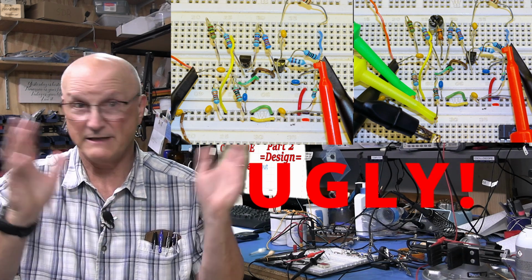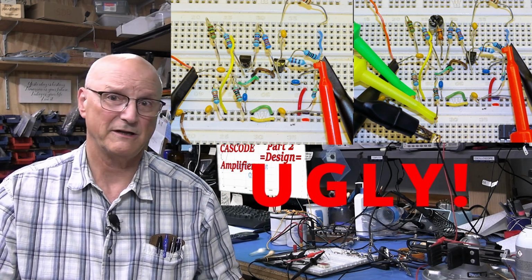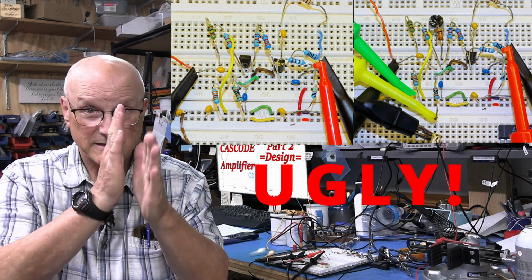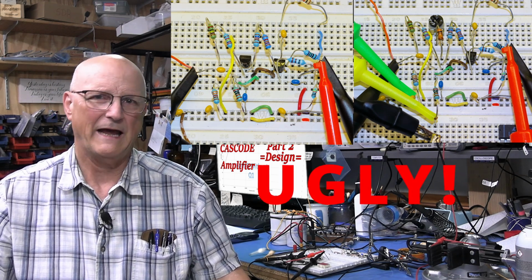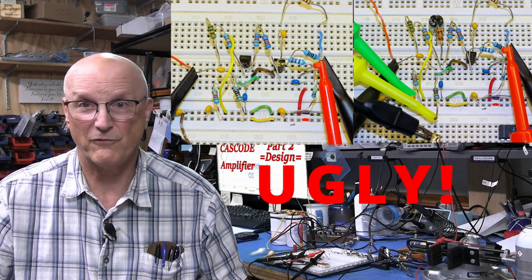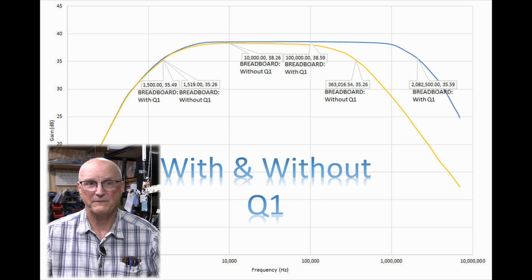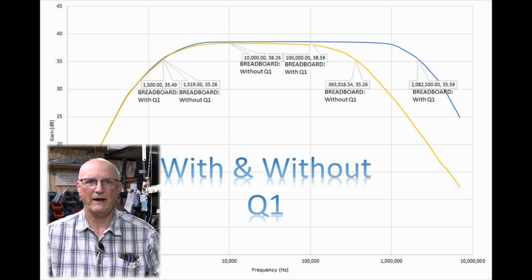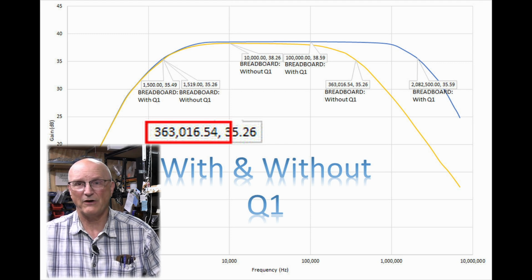Now, there's added inductance with the long leads of all these different resistors. Additionally, the breadboard itself has a lot of capacitance associated with its side-by-side rows of connections. And with all of this in mind, I didn't have very high expectations for its performance. So, let's see what the actual measurements came out to be. Here are the measurement results placed side by side on the same graph. The high-end frequency response of the common emitter amplifier rolls off at about 363 kilohertz.